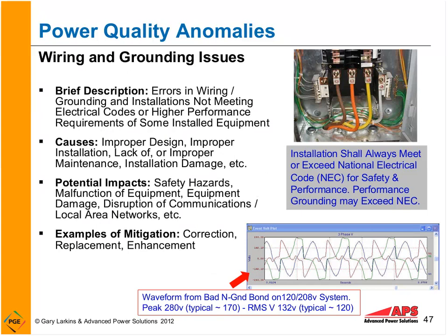Wiring and grounding. This is one of the most important in a facility. When we do our inspections, we go through and look for wiring and grounding errors. The installation always has to meet the National Electrical Code. We can't have wiring and grounding errors. Even if it was installed by licensed personnel, sometimes errors are made or equipment has an issue inside of it. So if we have wiring and grounding errors, that's going to show up in either failures or malfunction of equipment.